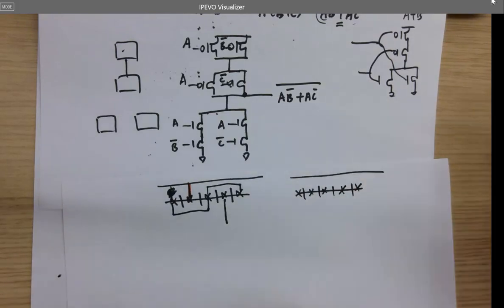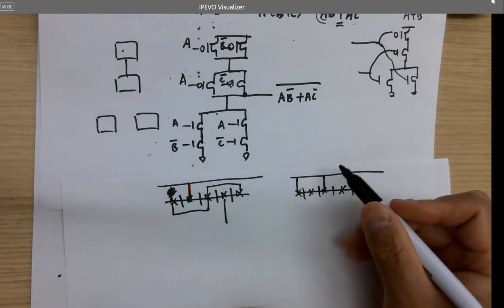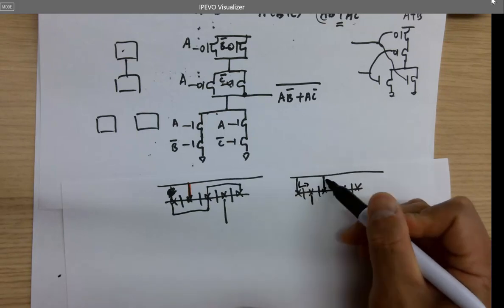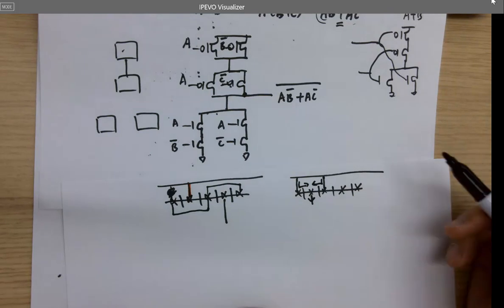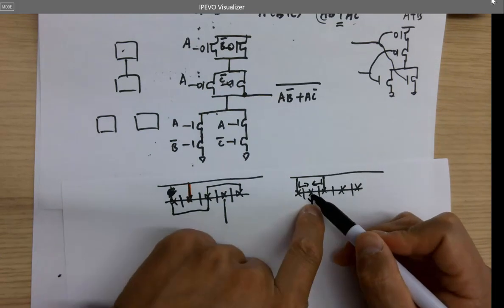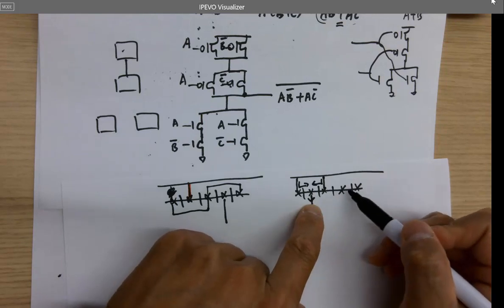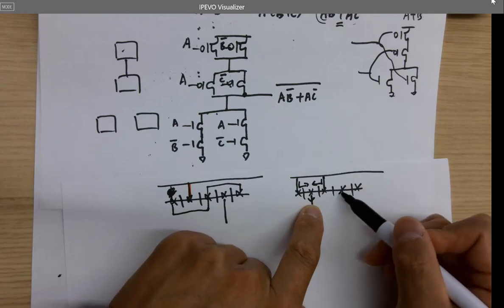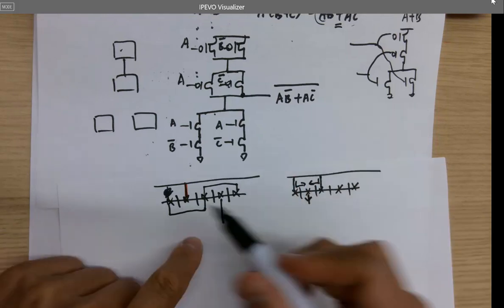Okay. So if I introduce 2 power rails from the top and then get 1 in the middle, it's 2 parallel transistors, right? And merge. And this node doesn't have any connection with these 2 transistors. It's going to fail. You know what I mean? Because it's one stick, this is already connected to the second block. So you cannot introduce the 2 wires and parallel transistors in that way. So I have to do it this way.